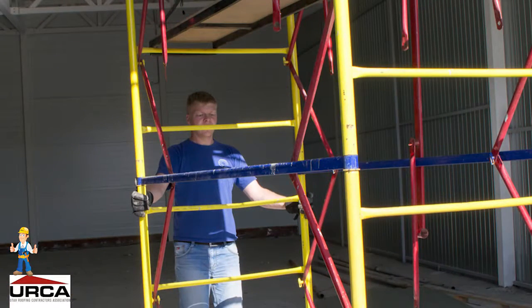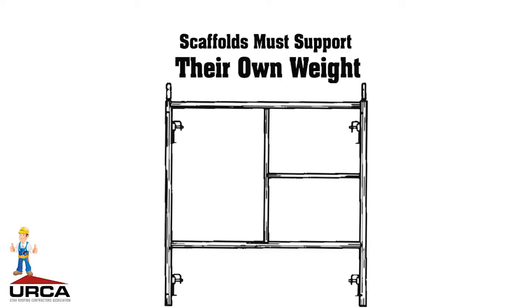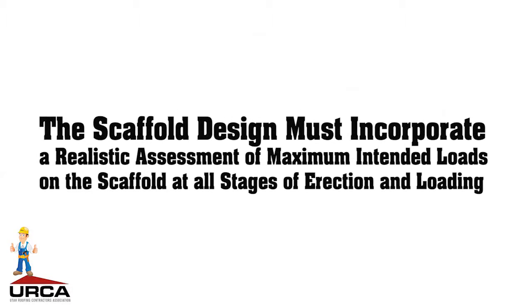Scaffolds must be designed by a qualified or competent person and built and loaded to design and erected by trained employees. The erected scaffolds must support its own weight and at least 4 times the maximum intended load. To accomplish this, the scaffold design must incorporate a realistic assessment of maximum intended loads on the scaffold at all stages of erection and loading.